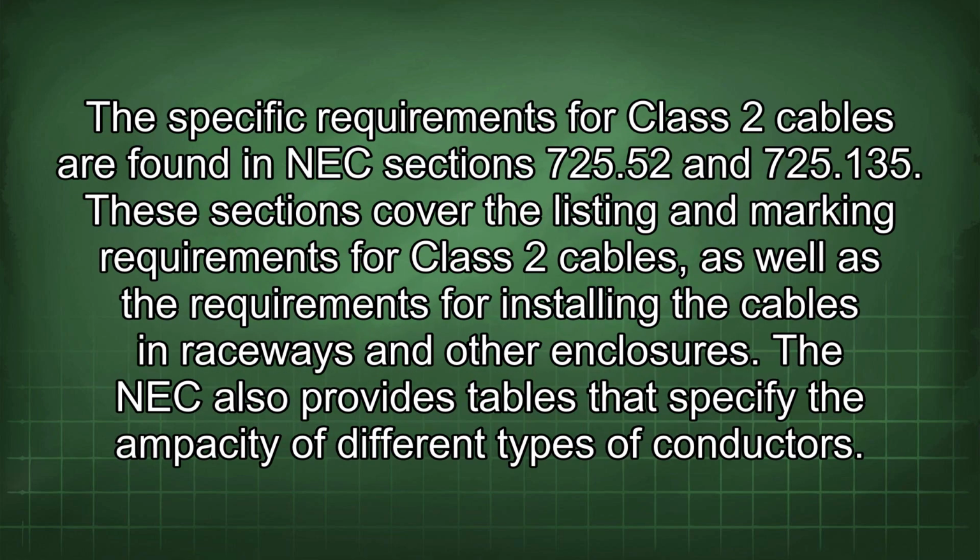The specific requirements for Class 2 cables are found in NEC Section 725.52 and 725.135. These sections cover the listing and marking requirements for Class 2 cables, as well as the requirements for installing the cables in raceways and other enclosures.